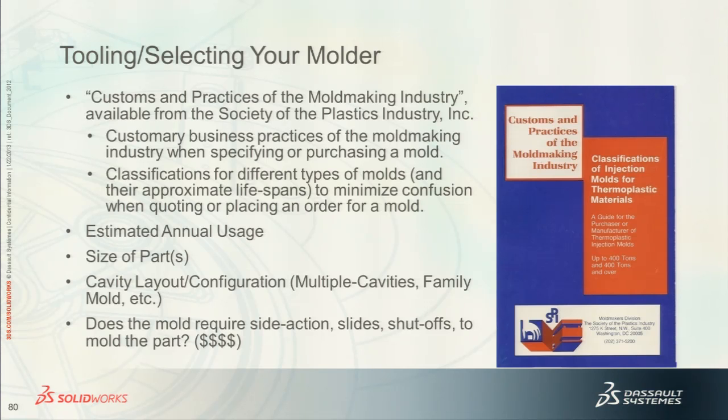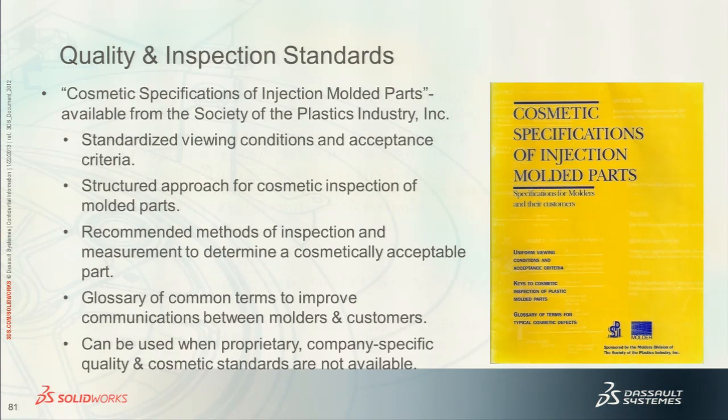Whereas I've done some disposable medical packaging where the volumes are much smaller. I would not necessarily need that robust a tool steel for materials that I've used for the disposable meds. So it gives you an idea of the different levels of manufacturing volume that you would have to address when you're specifying tools.